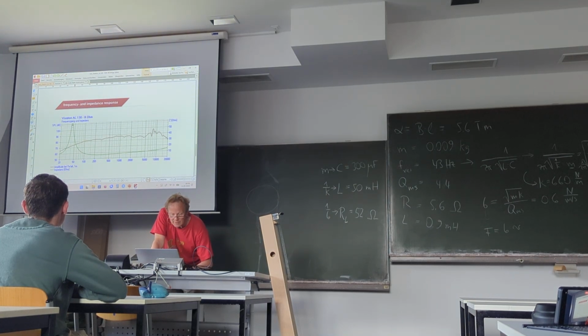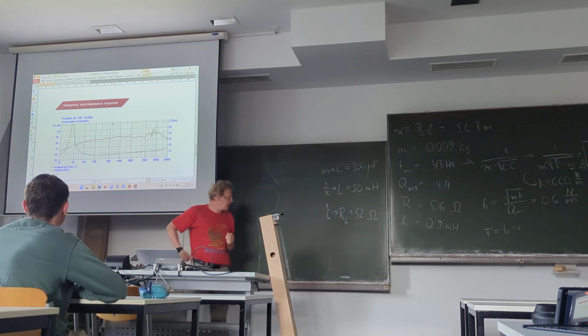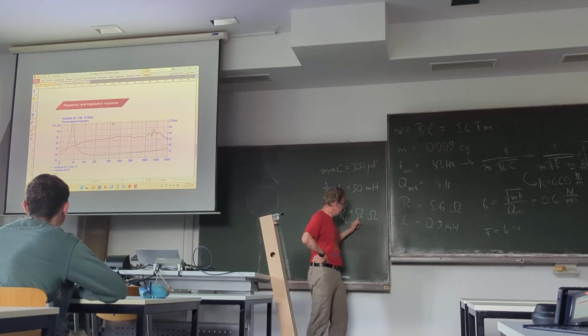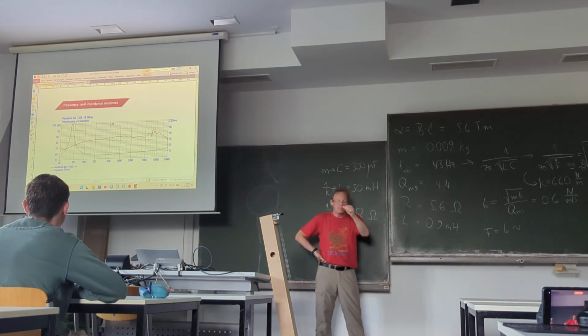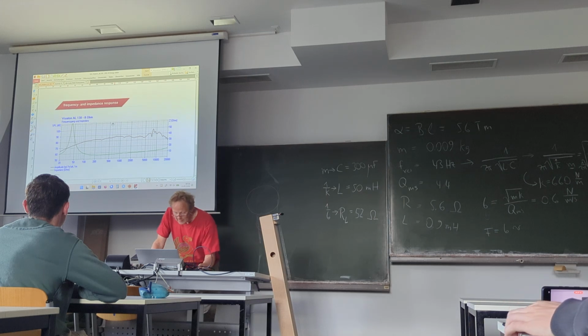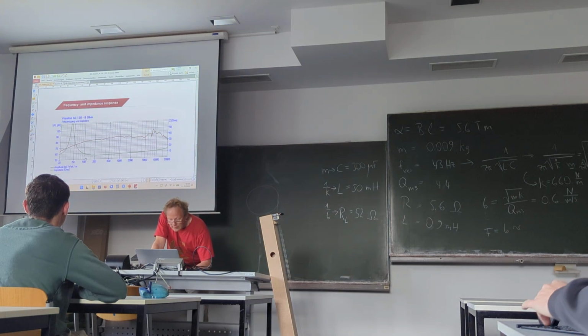And for resonance, we have this peak, we have the maximum, and actually, yes, okay, in this special curve we have a little bit more than 60 ohms. And I think with that idea, we know where it comes from. It's the sum of these 52 plus 5.6 plus some measurement errors. But that's why we have not only these 5 ohms.